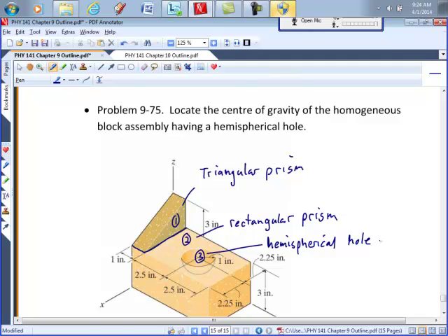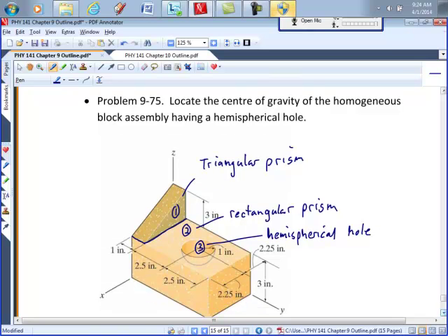So for each of these three sections, we're going to have to calculate a volume, and find the x tilde, y tilde, z tilde of the centroids. Basically do the same thing that we did for the areas in the past two problems, except that we've got 2 more columns in our table because we have 3 components of our centroid.